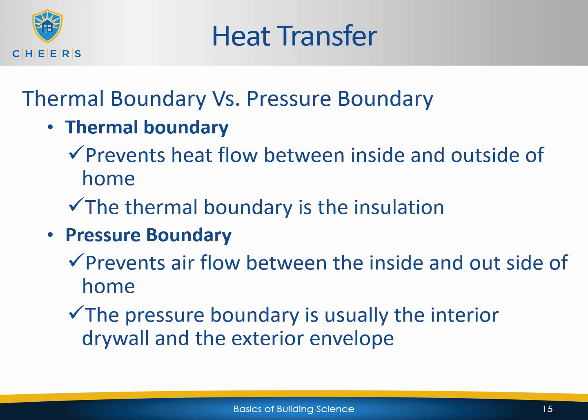But the pressure boundary is not necessarily the case. We're going to be covering quality insulation, installation, and pressure boundaries in other sections later. But just to give you an idea, if you have a double wall, the wall that you're looking at from the inside of the house might be drywall, but the pressure boundary actually might be set behind that wall, covered in drywall. So it's not always as obvious as you may think. Depending on the structural complexity of the house, the simple drywall that you're seeing from the inside of the house doesn't necessarily mean that is the pressure boundary.